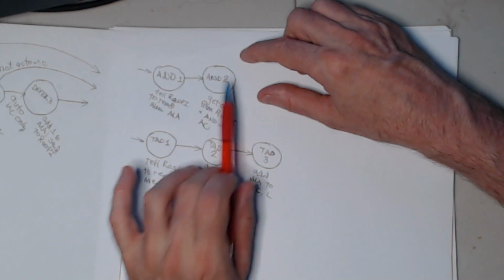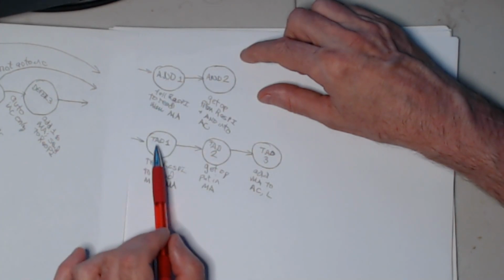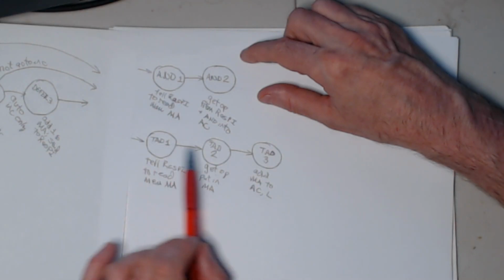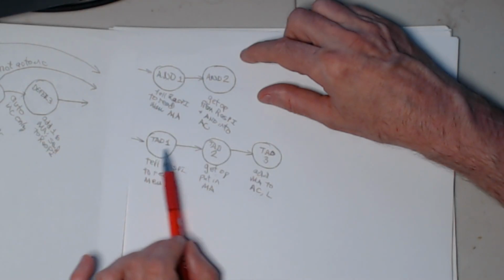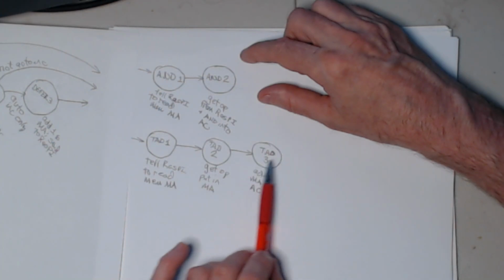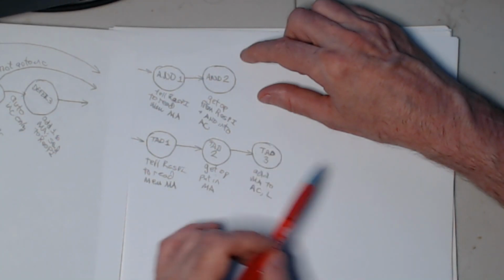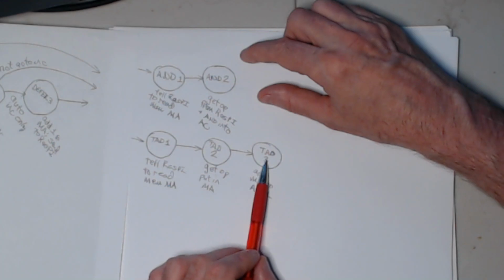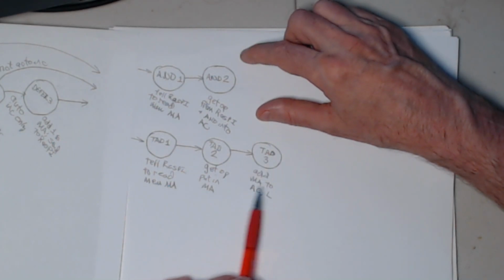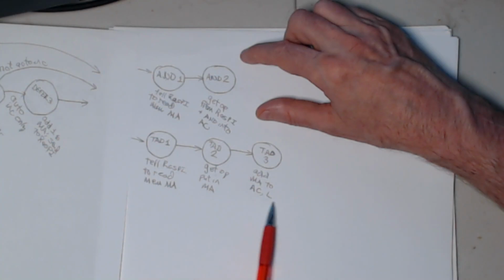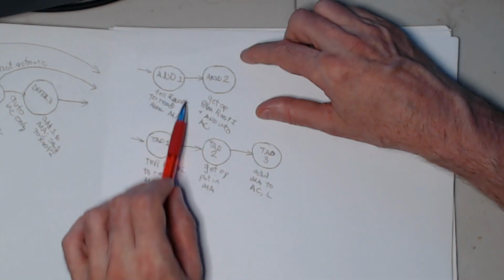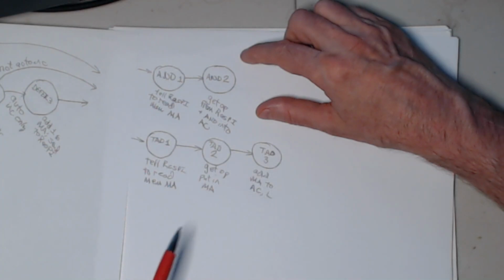Well, that's just a little thing, but mostly the TAD instruction in general takes 3 cycles, and you have 1 cycle here that's doing nothing but letting it soak through the ALU to do a full add, to update the accumulator and link. So that's the AND instruction, the TAD instruction.